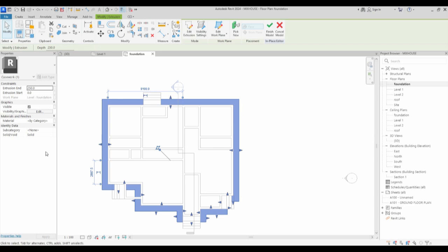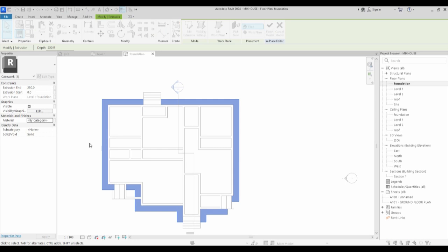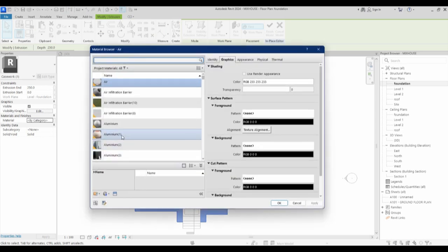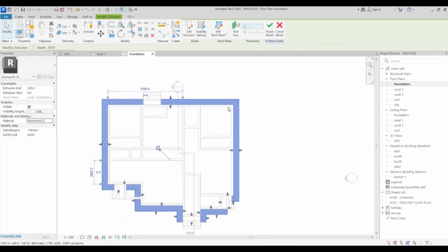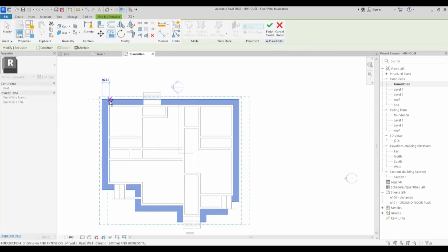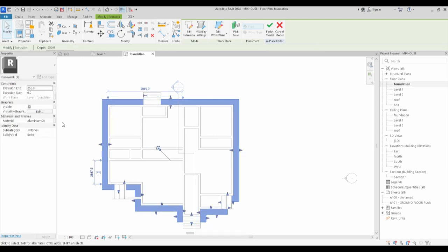Click. What we need to do is change the material for this. So double click. The material catalog will be there, change. What we do is just a pure white for the external. Now we copy this and repeat what we have done before in a systematic way. Escape, then you say this one increase it to 300 so that you have visibility of it.